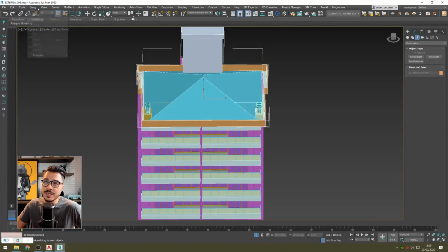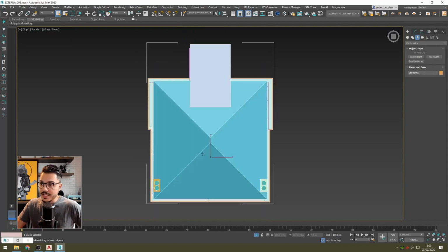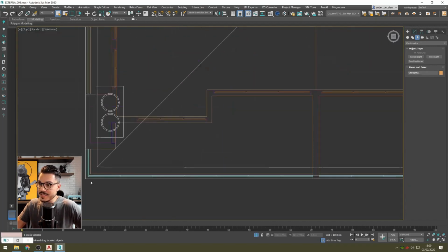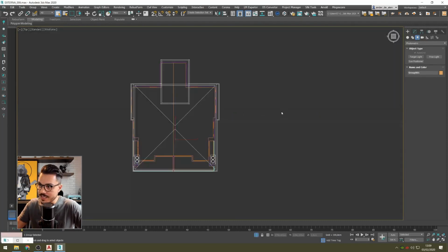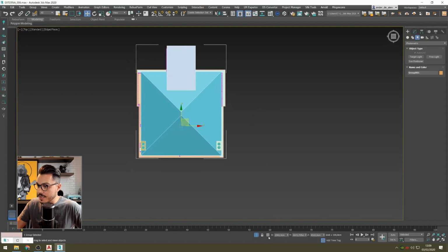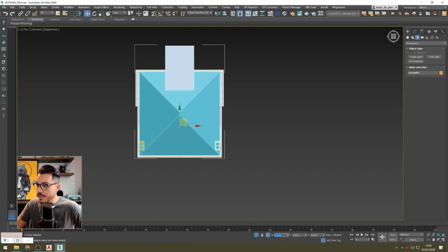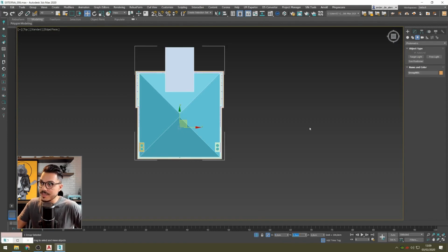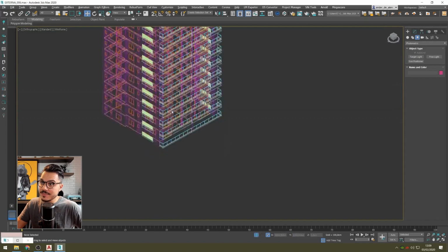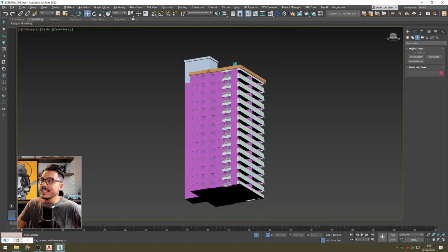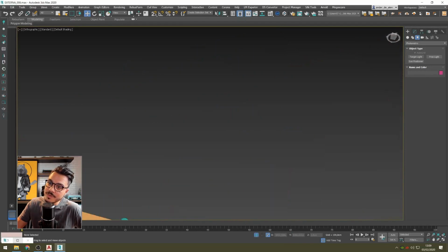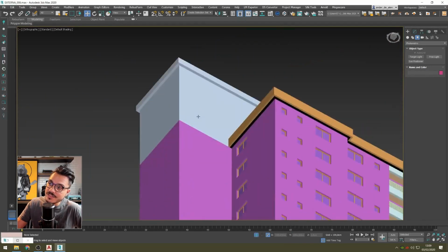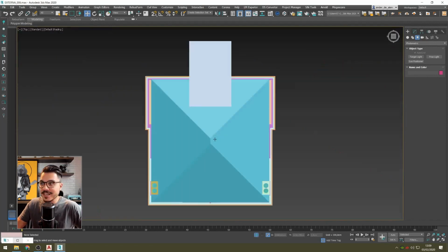I will click here, select it. I'm gonna even group it. Okay? And as I put corner to corner, and it shouldn't be, actually, it's 32 centimeters lower and 32 centimeters to the right. I go to move and click here, and in X, I set to -32, and in Y, -32. Now, let's take a look how it's going to be. It looks like it's correct now. Look, it's all... Just take a look. Very cool. It's attached.